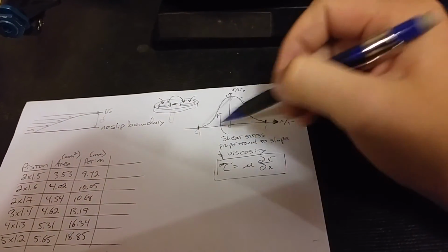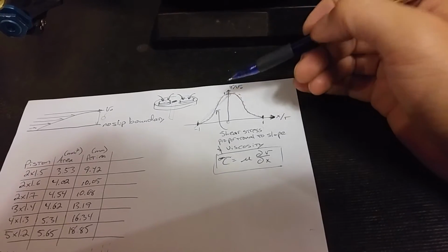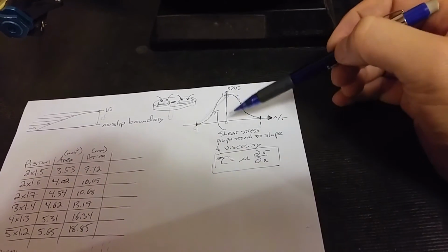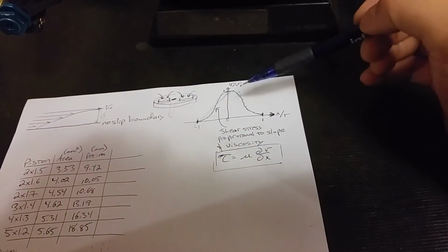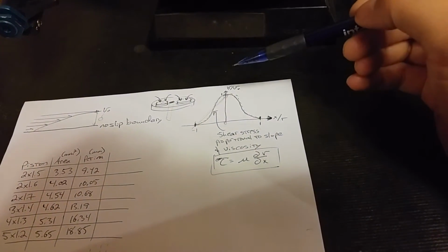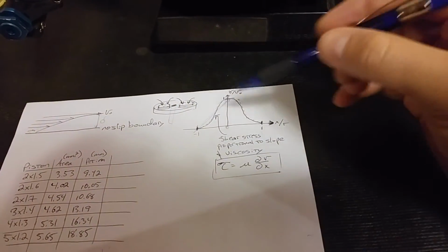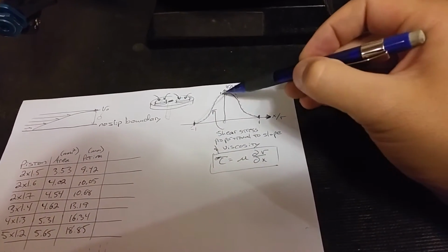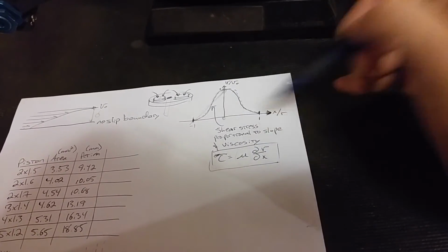within this fluid. Another way to view it is to say that if we want to move this piston up and down at a particular speed, it will require a particular amount of force, and that force depends on this gradient in addition to the viscosity of the shock oil.